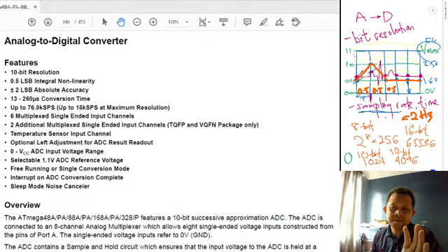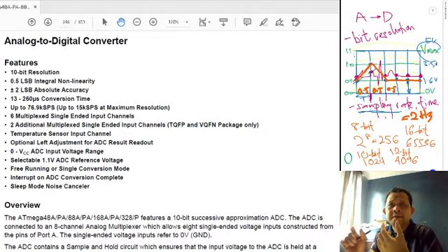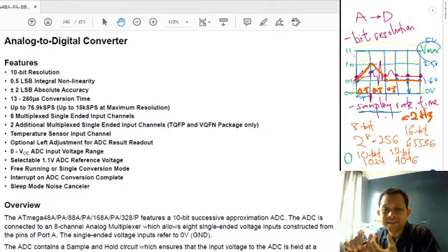Let's say for example, your memory is usually counted in terms of bytes. A byte means 8 bits. So if your ADC is 8 bit, one conversion is stored as 1 byte. If your ADC is 16 bit, that is 2 bytes. So you need 2 bytes to store the resulting value of your ADC for a 16 bit ADC.